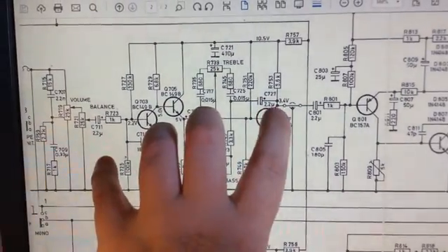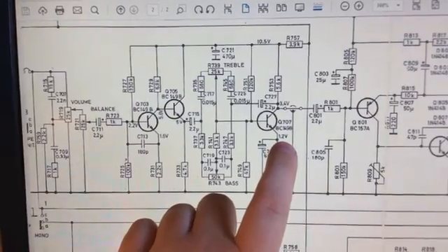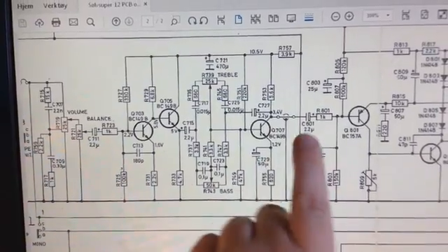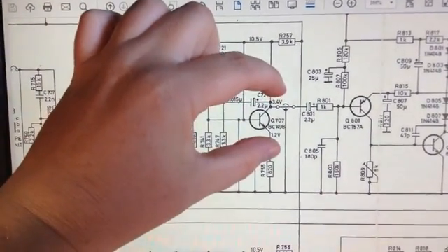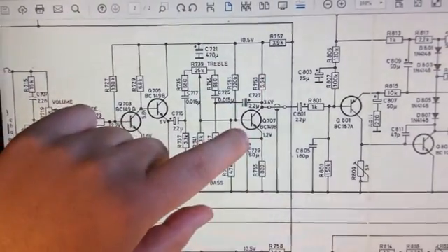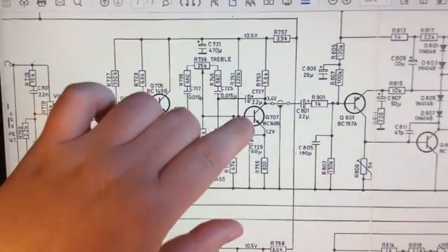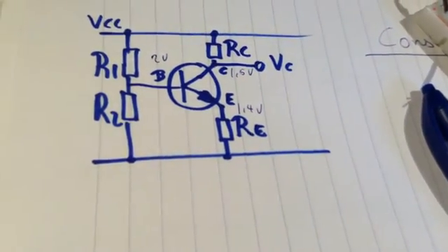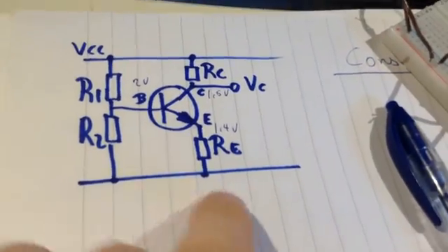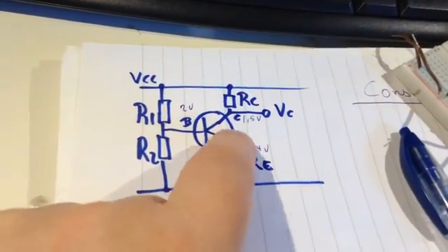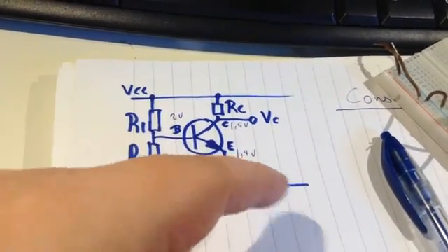when you measure DC, as you can see, this value here is much lower than he measured, and also the difference between these two values is much different. That means that this transistor in the schematic with these values will be in linear mode, but with these values then this transistor is in saturation. That means it's closed, it's like a switch, it is closed, so if you put a signal in on it, not much will happen on the output. Maybe you will get clipping sounds.